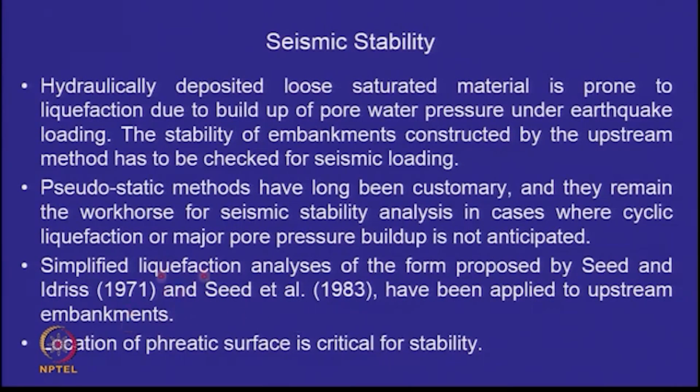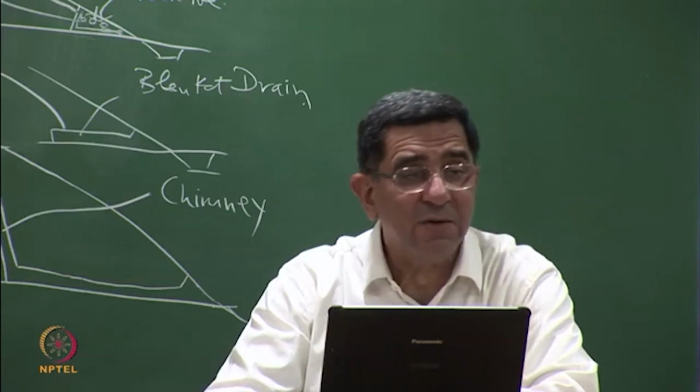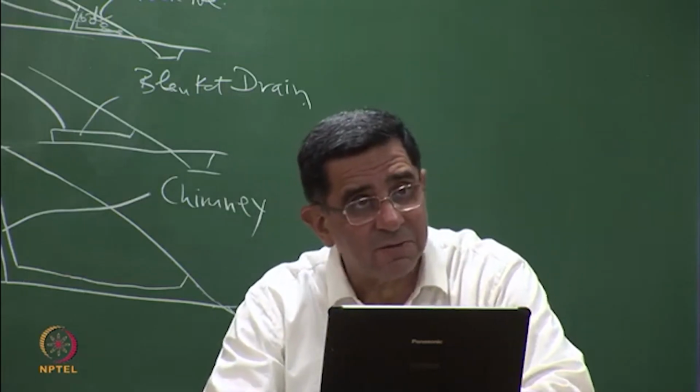So you have to do a liquefaction analysis for seismic stability. In all these conditions, the phreatic surface will remain the most critical. How high is your highest water level in the pond? How high is your highest phreatic line in the embankment? That will govern your stability.